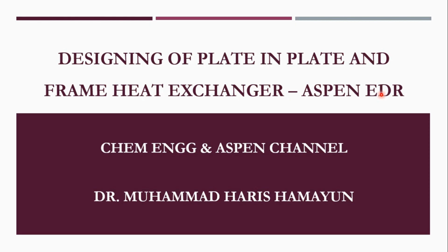In today's tutorial we are going to perform a rigorous design of a plate and frame heat exchanger using Aspen Exchanger Design and Rating, or we can call it Aspen EDR. Unlike a basic heat exchanger simulation, this tutorial focuses on the actual plate design and exchanger geometry along with the thermal and hydraulic requirements of the system.